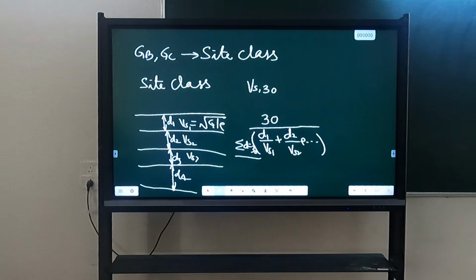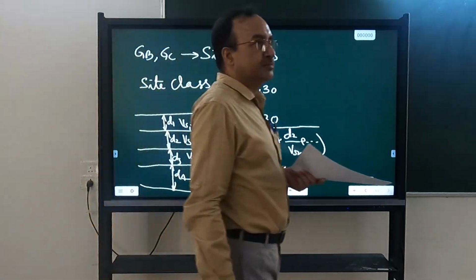One is the transducer of shear waves, another is the receiver. At different depths we transmit shear waves and receive them at the other borehole, and by taking the time difference and the distance, we can get the shear wave velocity. So that is the most accurate method.